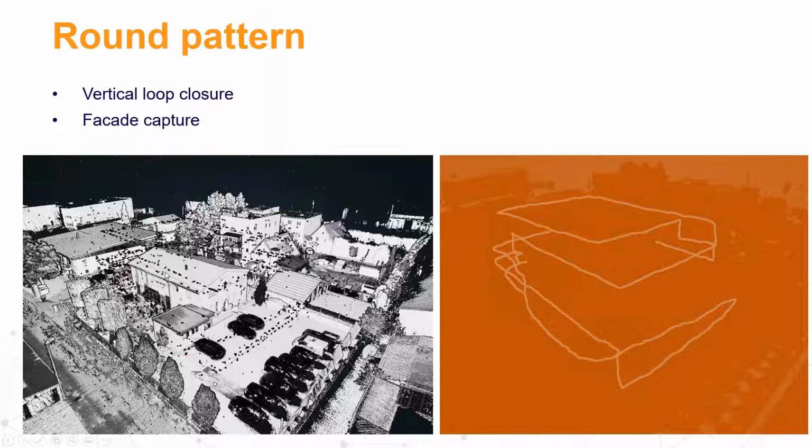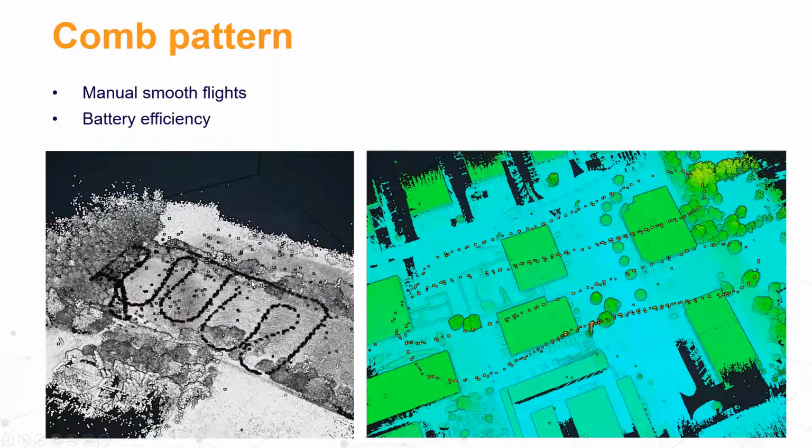So all those points that you see in the air, I just wanted to point them out as I kept them here on purpose. They are points that are scanned, part of the scanned propeller on the UAV. This is again something that you might want to change by changing the bounding box during the processing settings, as the Horizon is also pitched 20 degrees, which is better for the weight distribution if you're doing a handheld capture. But if you have the system mounted in the vehicle or on the UAV, the bounding box can get rid of all those close points from the given objects.